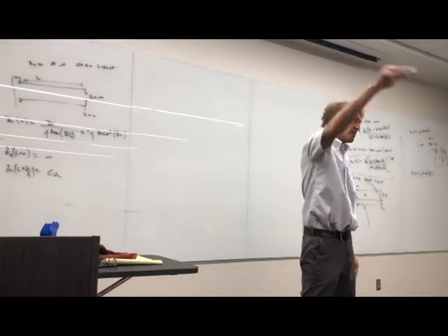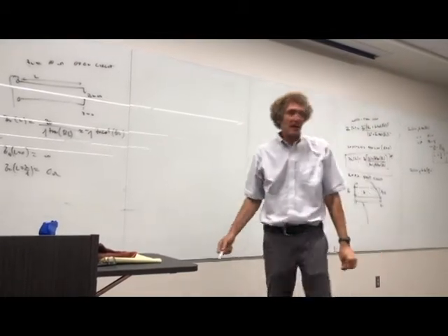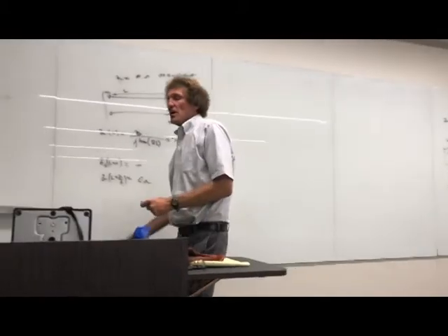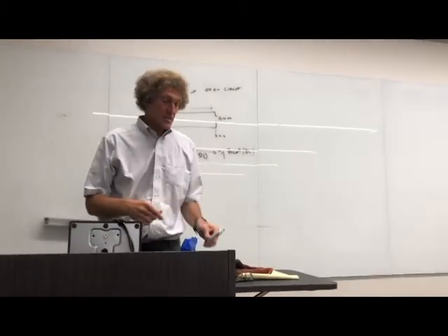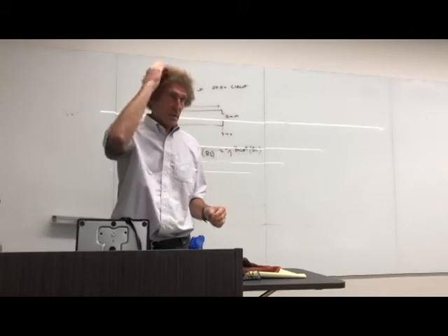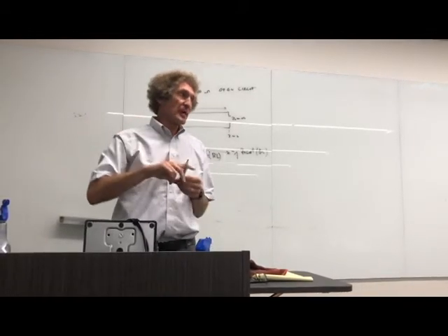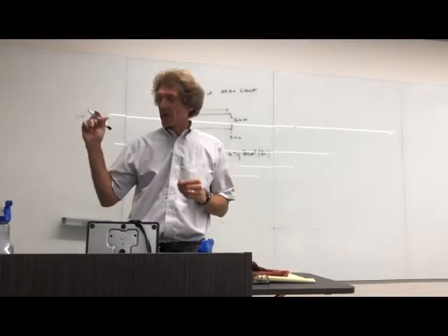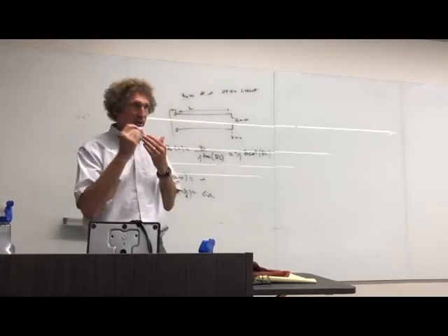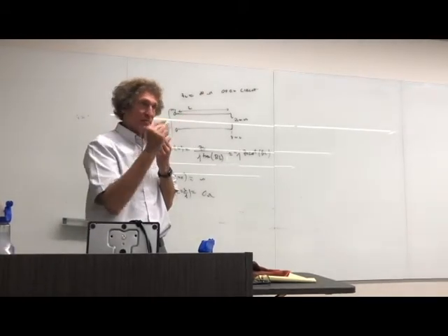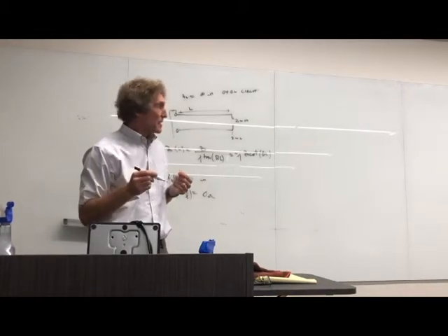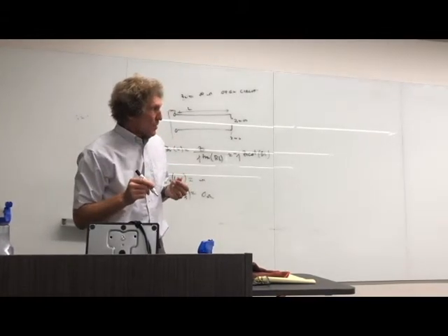When they string cable all over the place, you have no earthly idea how long it is electrically, but you can find out. We cap one end with a short, and then we do time domain reflectometry, and we can get that. It's really listening for how long it takes something to echo back after it bounces from one end to the other. All right.